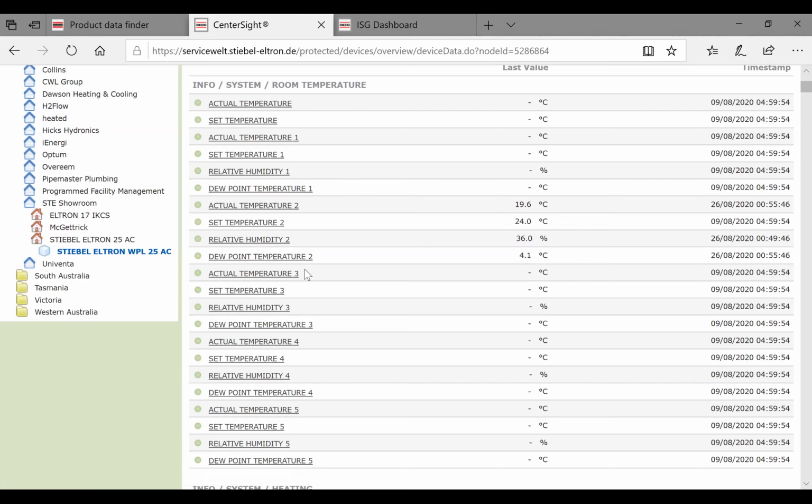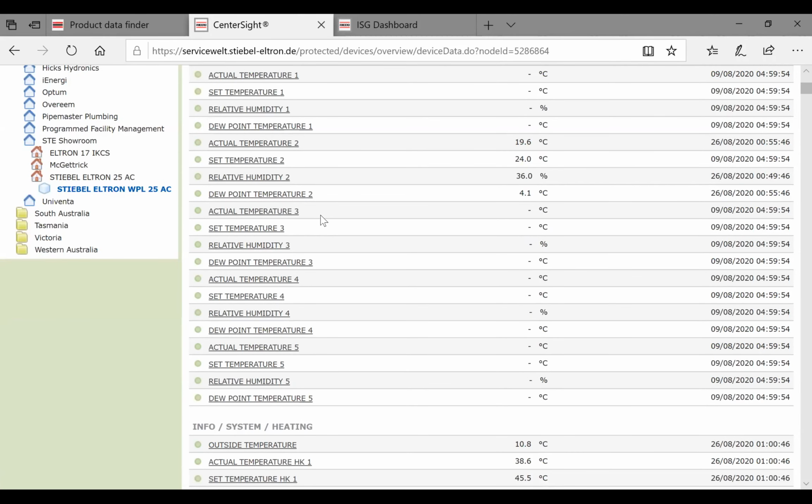Why we calculate the dew point is when we do surface cooling, i.e. when we want to turn that underfloor heating system into an underfloor cooling system, we want to be able to pump water at a temperature through the floor that will not cause condensation on that floor. So we will do a dew point calculation and we will keep the water flow 2 degrees above that dew point calc. That way there is no chance of any condensation forming on any of the floor surface or the pipe fittings or the manifold in the distribution system leading up to the floor.